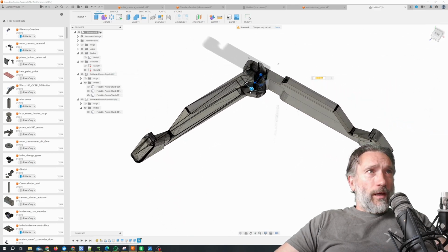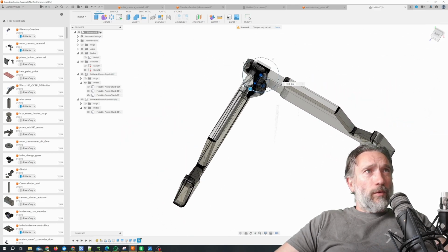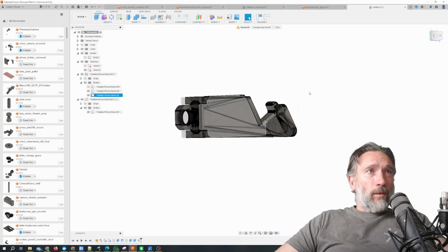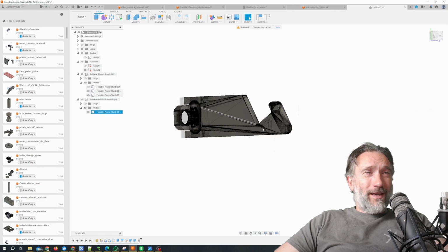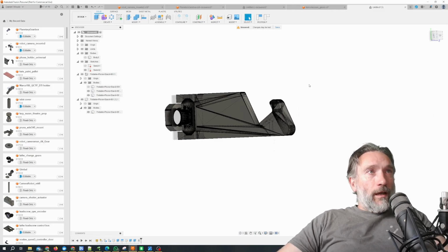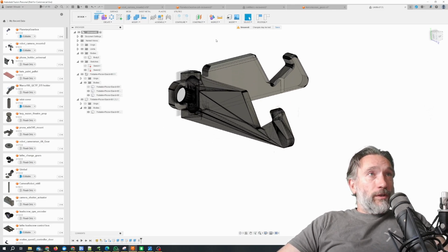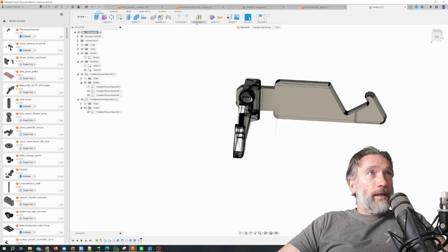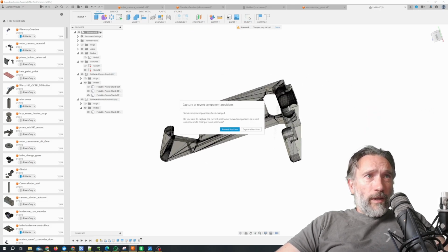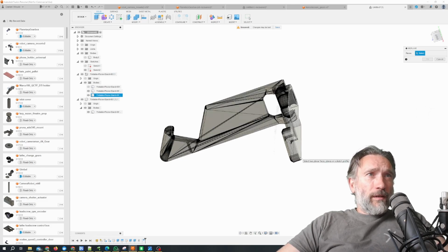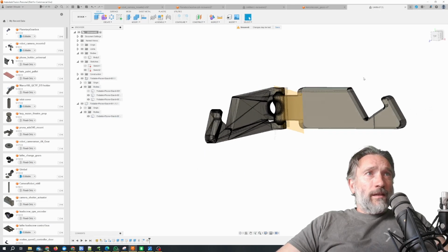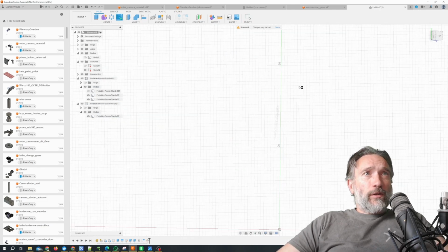So let's assume that a good angle for our stand is about 90 degrees. So what we want is this path through here to be big enough. What's a good way to do that? I think what we'll do is create a mid-plane. Let's create a mid-plane between, capture the position between you and you. So that's exactly the middle. And then we'll create a sketch on that mid-plane.